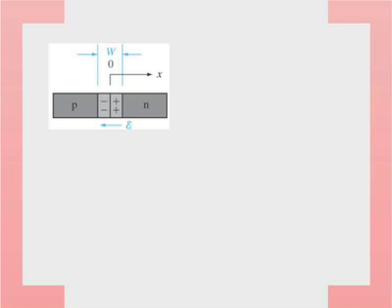Now, physically, what this means is that the electrons get captured by the silicon atoms, for instance, and you have uncompensated acceptors here. So essentially, charge neutrality is broken. You have excess charges here. We'll look at that more carefully. But essentially, you generate some charged regions here.